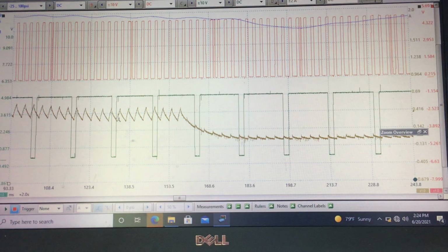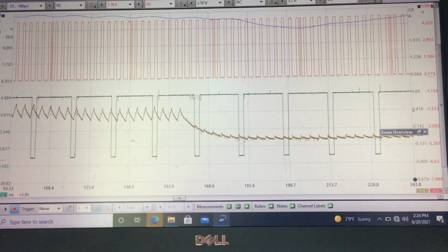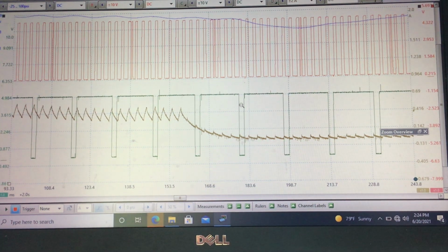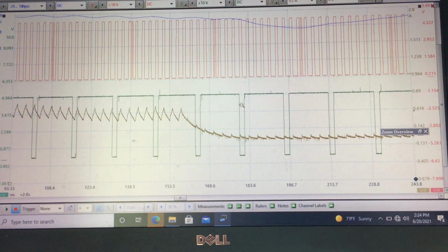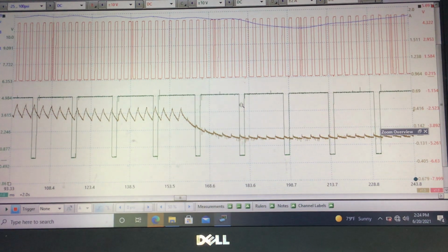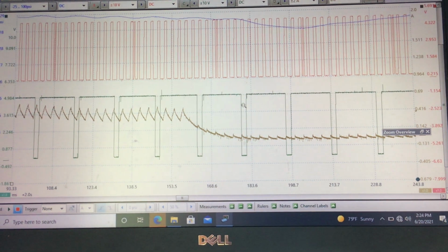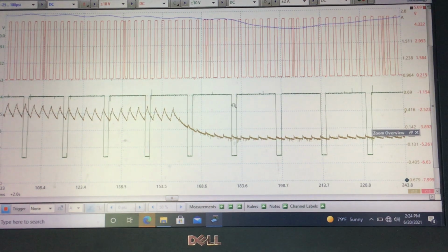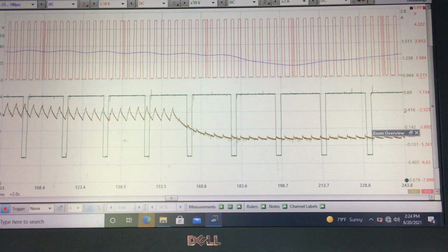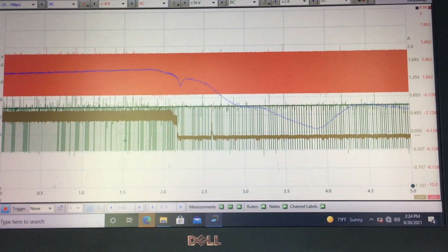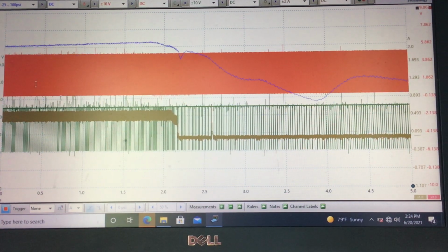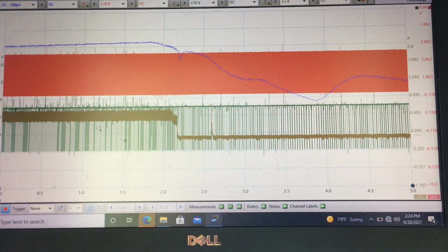As this duty cycle changes, this cam moves to the left, and the events of the cam lobe action on the intake cam happen sooner. So nonetheless, this technician signing off. Remember to be mindful of oil pressure. Not every time, but you realize the scan tool is important. You don't want to waste a lot of time. If you see need to check oil pressure, definitely consider it in your diagnosis. It is very important on any engine, but particularly when we have a variable valve timing issue.